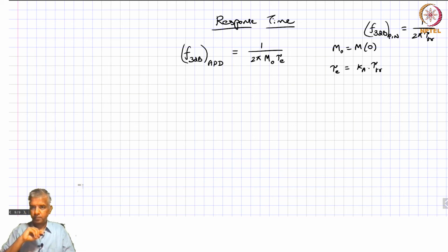Ka, like we said, can be a value of 0.5 for indium gallium arsenide, 0.1 for silicon, and correspondingly the gain value could be in the order of 10 for indium gallium arsenide, and in the order of 100 for silicon. But this is the trade-off now.